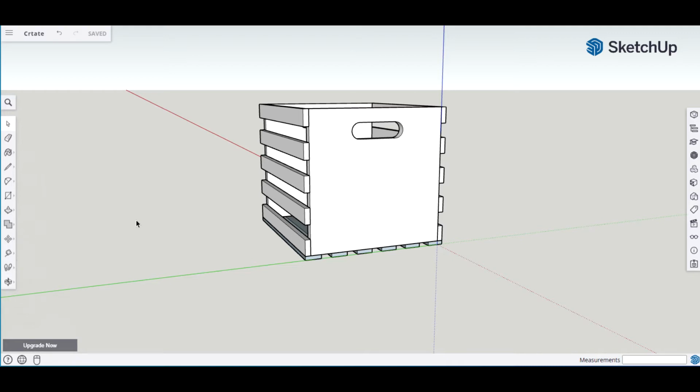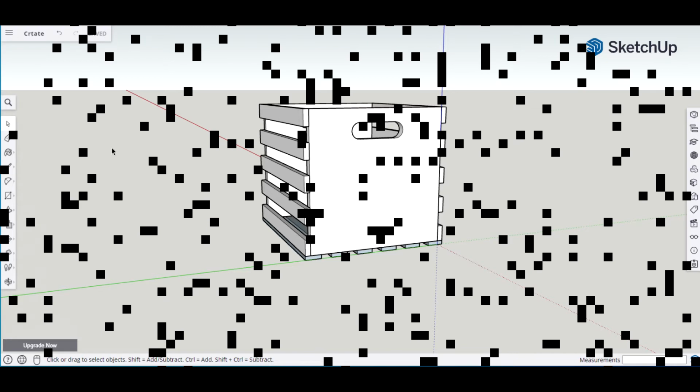Now, as I go through the drawing, I will give you shortcut keys on how to access the various tools that you saw in the tool callouts. For example, the line tool can be accessed by selecting L. And to get back to the select tool, you just hit the space bar. As I go through this project, I will always try to tell you what shortcut key I'm using so you can learn that way. So with that, let's continue on with creating this crate.